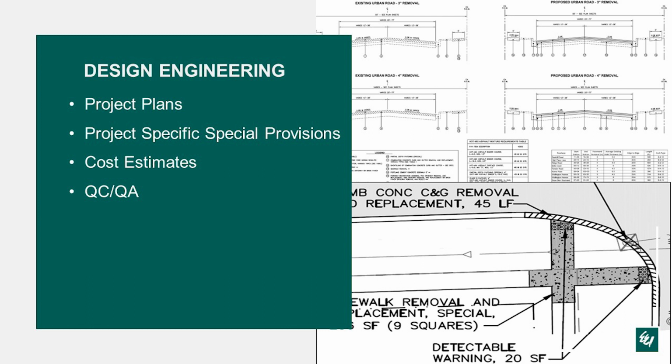One of the most important parts of these projects is the cost estimate, making sure that you have enough material in there so that it reduces the amount of change orders in the field or extras that come about. We also like to put in a little bit of fluff, especially on asphalt, for loss of material. Also, sometimes we add a couple of sidewalk squares, because when you're doing the ADA stuff, sometimes you end up having to replace more squares than you thought you would.